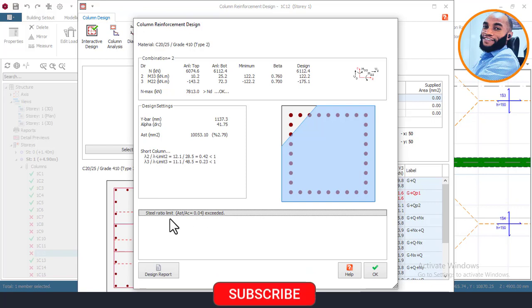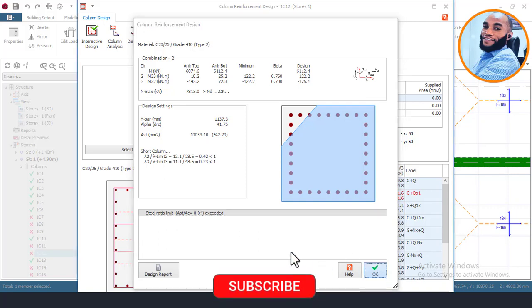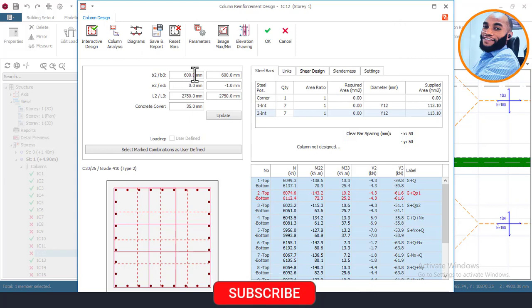You can now see that it says the steel ratio limit is exceeded. So I'll click OK because it's failing, and then I'll come here and increase the size of the column. Let's increase the size of the column to 650, and here too to 650.